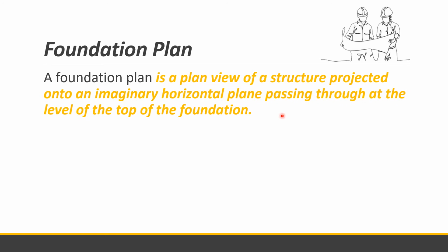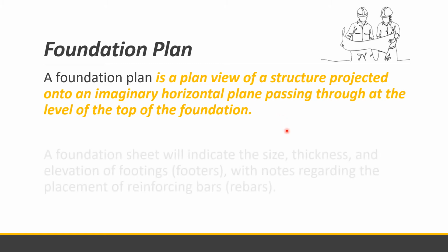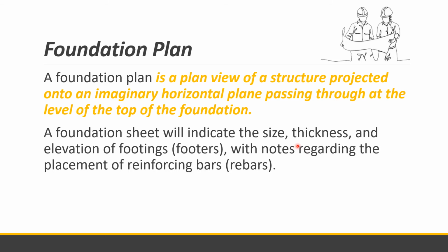So, first component or first drawing na makikita is the foundation plan. A foundation plan is a plan view of a structure projected onto an imaginary horizontal plane passing through at the level of the top of the foundation. A foundation sheet will indicate the size, thickness, and elevation of footings with notes regarding the placement of reinforcing bars.